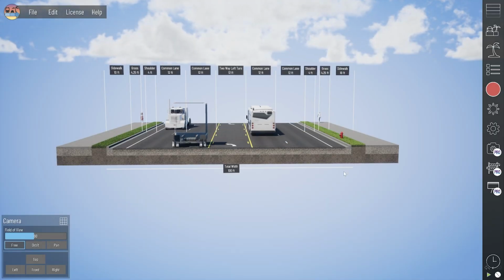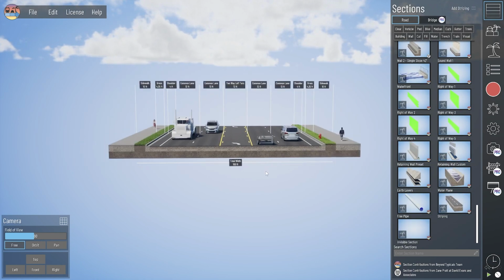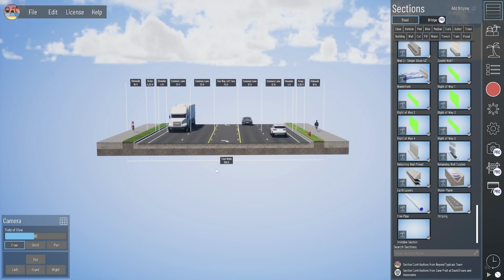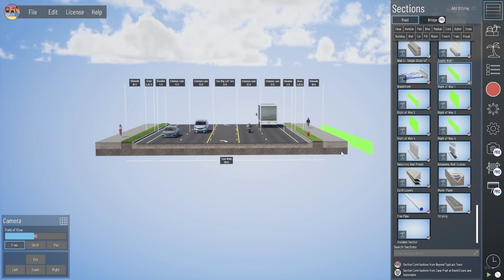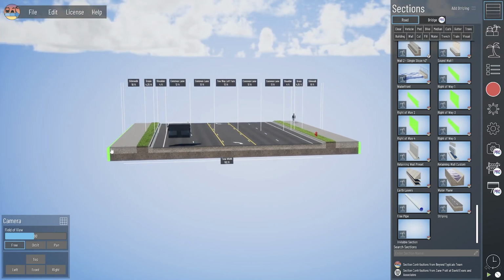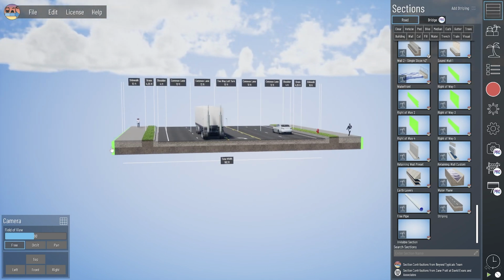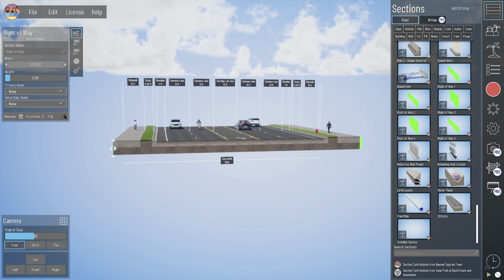One other use for our invisible sections is using the negative width to help counteract some other widths in your sections that you might not want to show in your total width and keep that total width dynamic. So one of these use cases could be right-of-way. Let's say we want to see right-of-way lines in our model, and we don't want the ones that extend over the top of the typical section elements. So in order to see that, we need to have a width assigned to that, because if we bring that all the way down to 0, that basically becomes invisible.